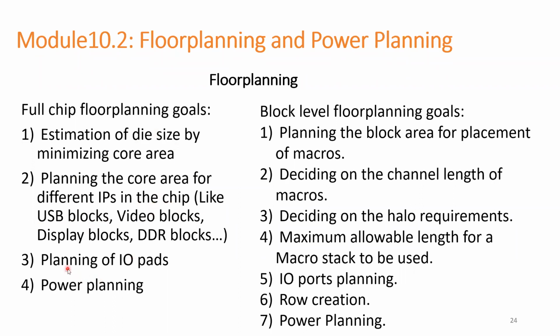So the full chip level engineer has to plan the IO pads, the input output pads. We need to get the desired location, where it gives better timing and better area. So based on all those analyses, the full chip engineer has to do the IO pad placement.